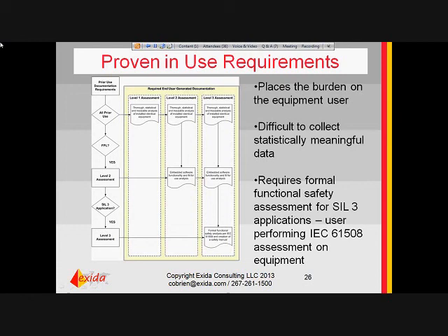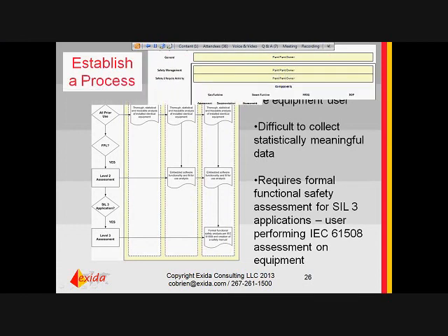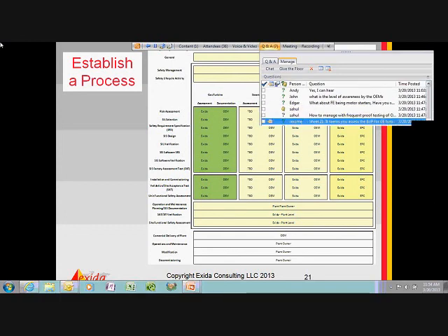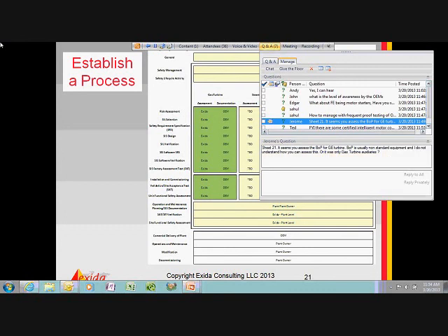There's a question on slide 21, about certifying the balance of plant. So this would be like a 61511 assessment of a plant. You could go to the extreme where in the balance of plant there were no SIFs, but in certain countries, Australia specifically, the authorities are looking for assessments and evaluation of the installation.